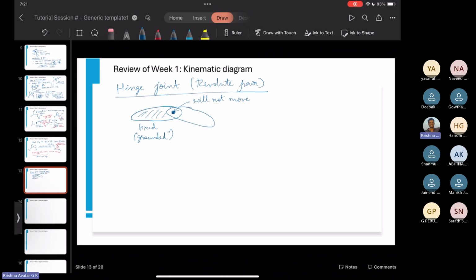So this joint or this pair here will not move. Joint is essentially this. This will not move. Which means that although this body in planar state had 3 degrees of freedom, because its one point is fixed, because if a rigid body, if any point is fixed, then it places constraint on all the points. This point is fixed means even this point also does not have freedom, since this is fixed, right?